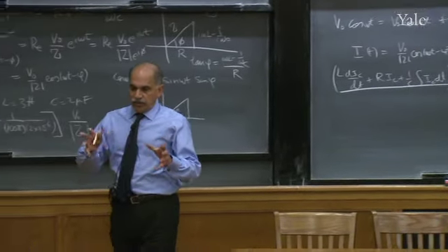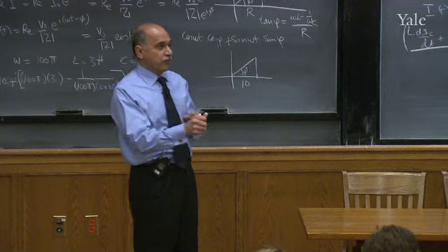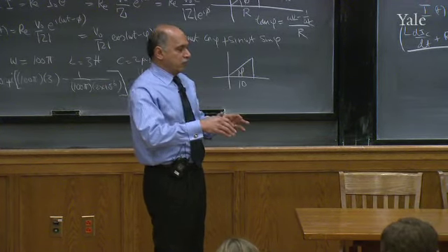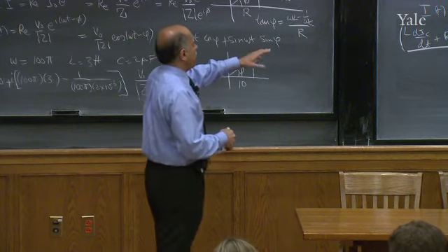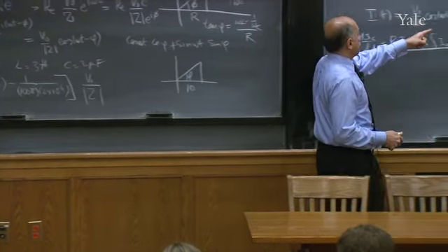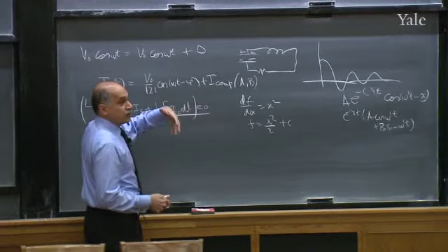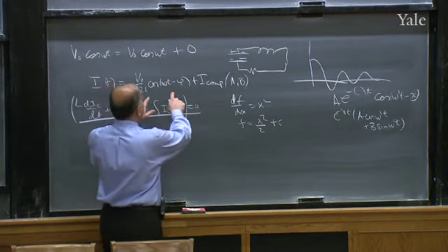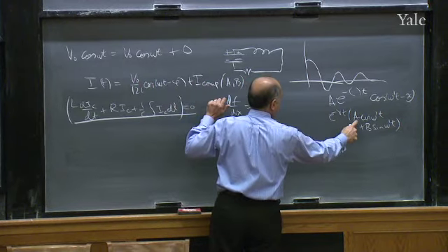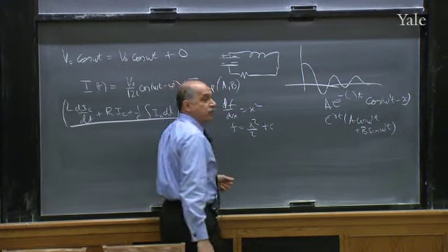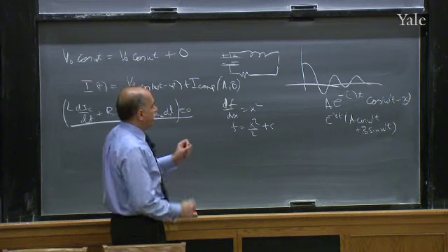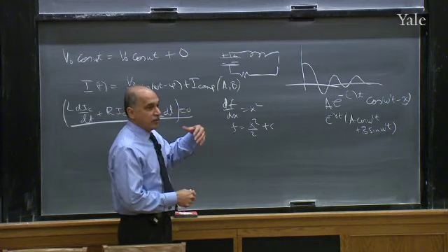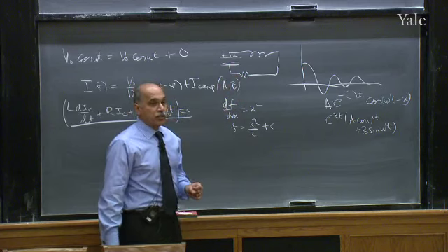In other words, if you took the LCR circuit and took a generator and you hooked it up, from the instant you hooked it up, it won't immediately assume this form that I have here. Because, for example, at t equal to 0, maybe the current is 0 in the real problem. This current doesn't vanish. But you should add to this function, choosing a and b so that the current vanishes at t equal to 0. You can fit the actual experiment to the solution by choosing a and b to match the initial current and say the initial charge on the capacitor.